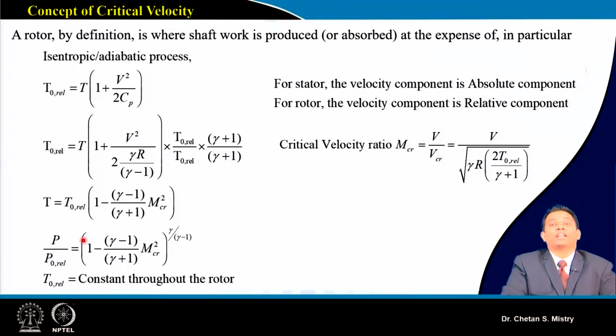The data that may be available with you are pressure, maybe the static pressure at the hub and at the tip. By using thermocouples, we can have the temperature values. Maybe for the design configuration, mass flow rate is known to me or it may not be known. Rotational speed data is also available with me.